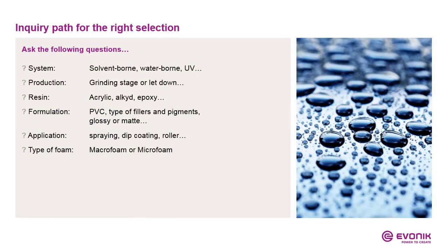In order to give the right recommendation to the customer, we have to ask the following questions. What kind of system is this? Is this a solvent-borne, waterborne, or UV? And the production type. Are we incorporating the additive inside the grinding stage or at the letdown stage? And the type of resin. Is it acrylic, alkyd, epoxy?